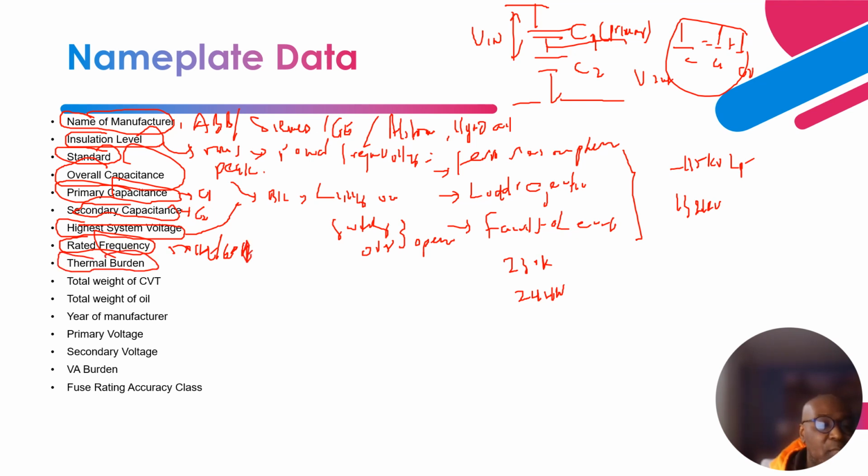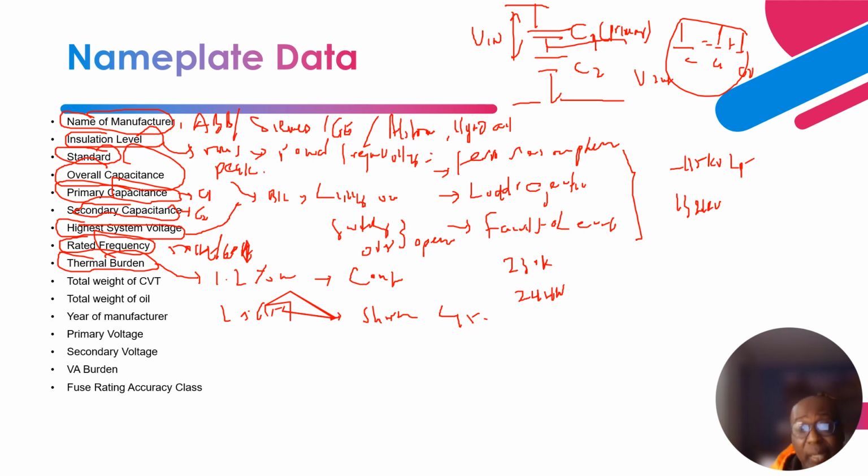Then the thermal burden usually comes into play. If you choose to go over voltage, that is 120% of the nominal voltage, with a duration of, let's say, continuous. And 1.5, that is 150%, has to be for a shorter duration, let's say about 45 minutes. If you're operating above the nominal voltage rating, at 120% and 150%, that is definitely going to result in heat. That is why you have the thermal burden, so that you can operate in these conditions.